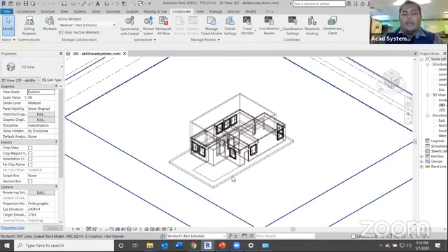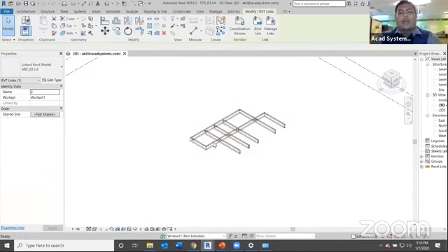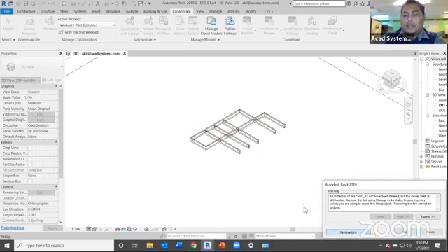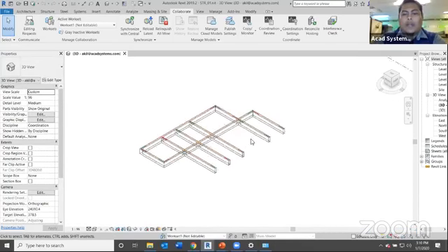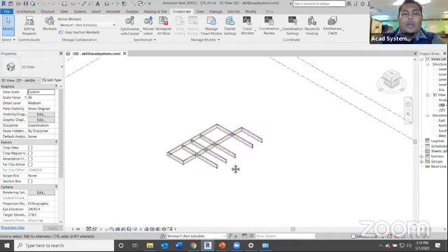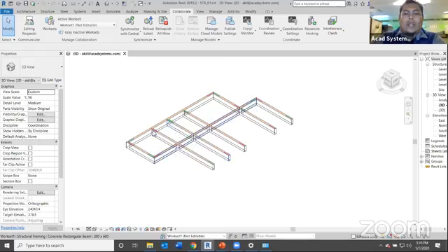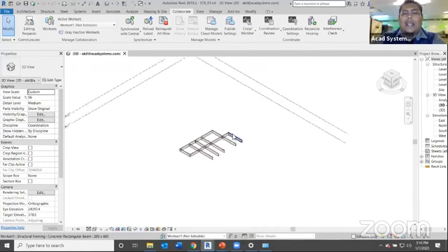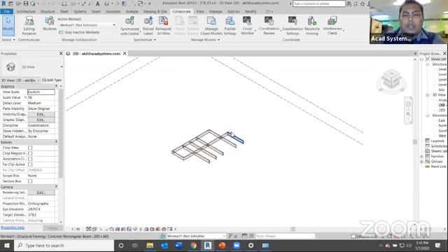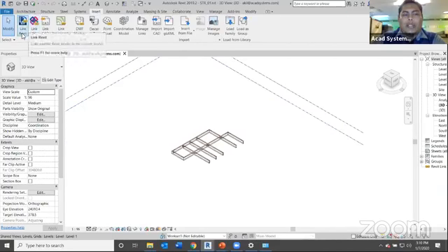Let's say there is a link that I removed for now. I'm going to show you later how we work with that link. There are structural models that you need to finish, and you have to link the architectural drawings for your usage. If you're going to link, usually people will use this Insert Revit Link.